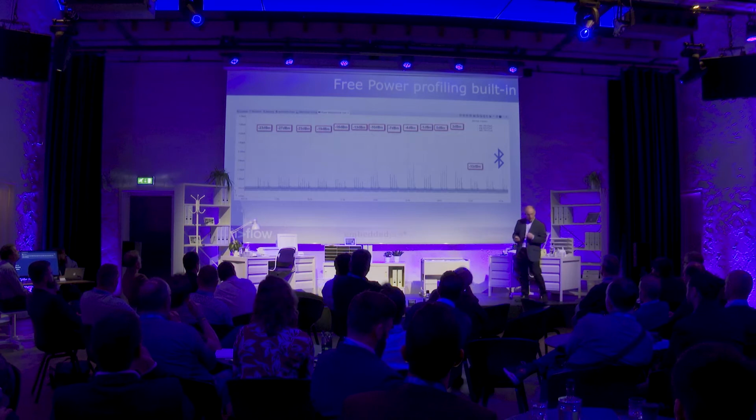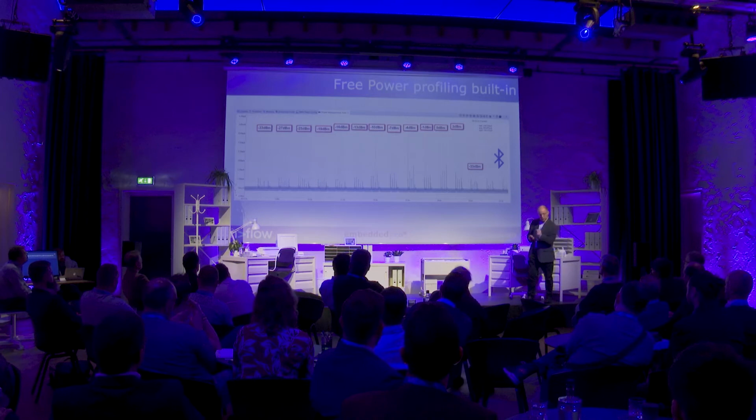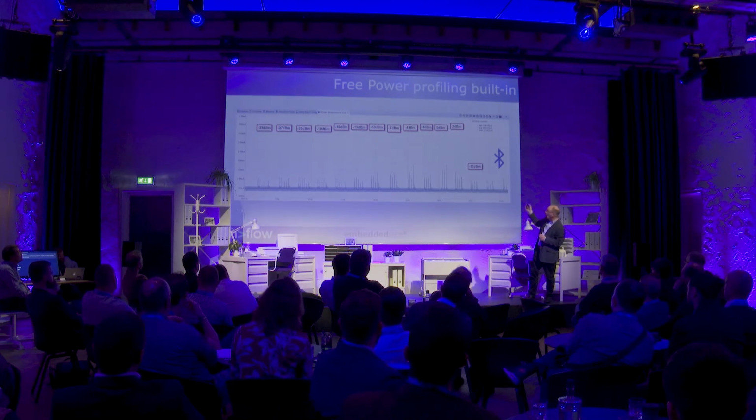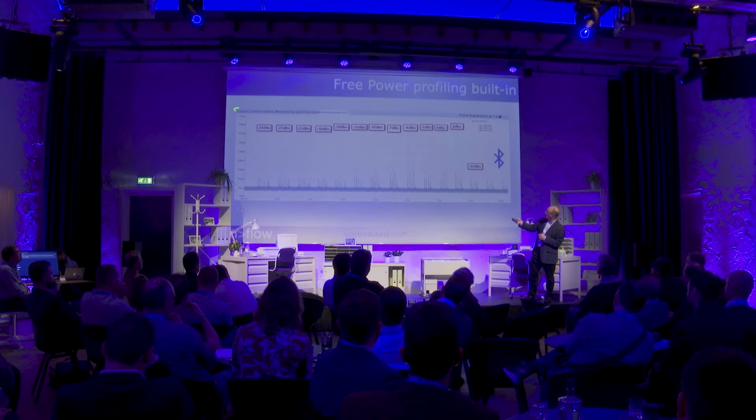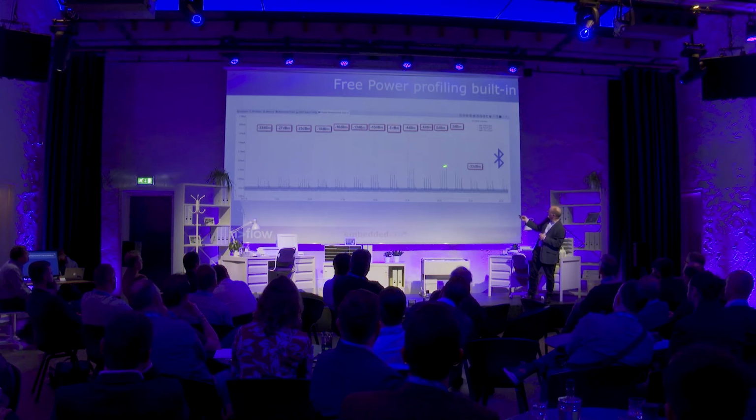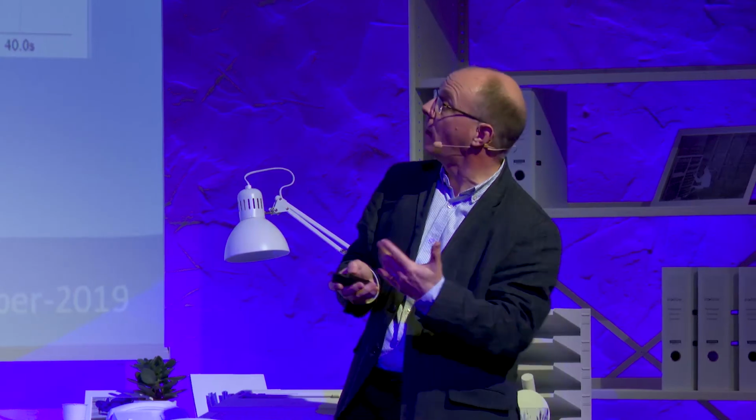You don't need an expensive probe. On a supplier's development board, they've got a jumper that can be put in place, and their free development environment has got this power profiling tool. And the same as the expensive probe, whilst the software is running, we're able to measure how much current the microcontroller is taking. And here's a test I did on a Bluetooth radio, and we were just changing the output power and looking to see how the current consumption was increasing as the output power was ramping up.